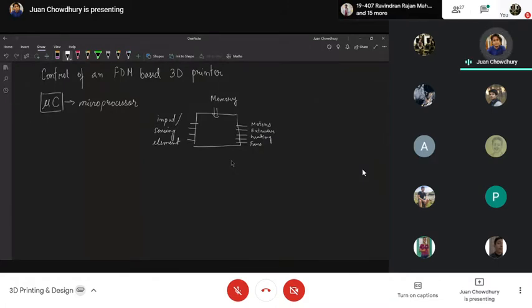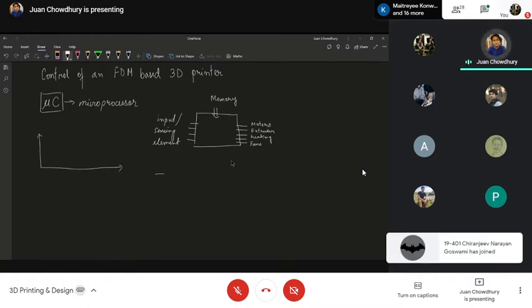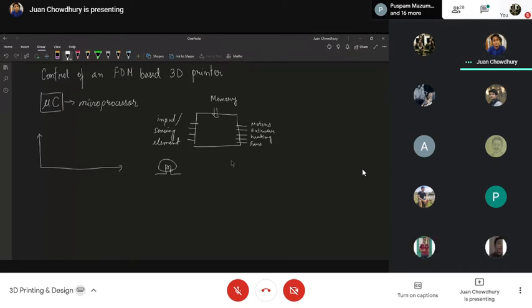So what a microprocessor does is it converts this information and creates some binary voltage signals. Most conveniently, what is used is something called PWM, which is a pulse width modulated signal. So let's start with a concept that if I want to turn on and off a simple LED light bulb, then I want voltage in and voltage out. That's very easy to understand.